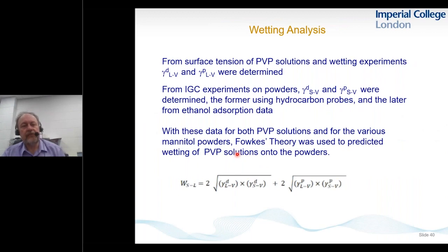So part of what we're going to do now is determine, using the wettability information from the IGC data for the materials, whether the PVP solutions should wet or not wet our powders. Clearly, some powders are hydrophobic and some are hydrophilic, so we want to see which ones are going to wet and which ones are not going to wet.